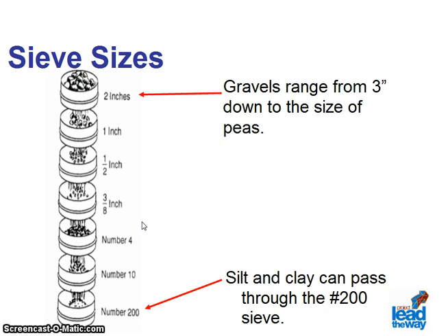Sand, the finest of grains, start just below this size and decrease until the individual grains are about 0.07 millimeter in size, about the size of a number 200 sieve. Silt and clay particles, those which pass through the number 200 sieve, are indistinguishable as individual particles. In fact, they cannot be seen by the naked eye when viewed at a distance of 8 inches.